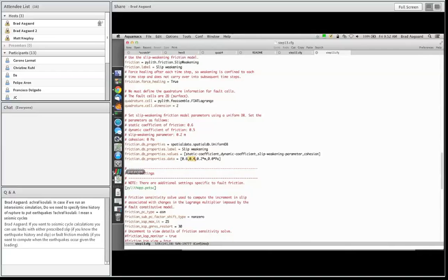We may have a uniform slip in that one, but later we have a depth-dependent slip distribution, and I believe it's step 20 where we have a non-uniform traction. As soon as we run this example, we can take a look at that, and I can show you how to look at the boundary condition in ParaView.